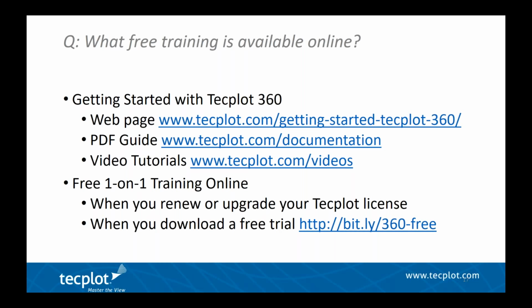And let me read this one. Is the new slice extraction feature available in PyTecplot? Yeah, the answer is yes. Any feature that goes into Tecplot 360 is going to be available to the Python layer as well. PyTecplot does get updated along with Tecplot 360. So, as long as you have Tecplot 360 Release 3 and install the latest PyTecplot, you should have that capability.